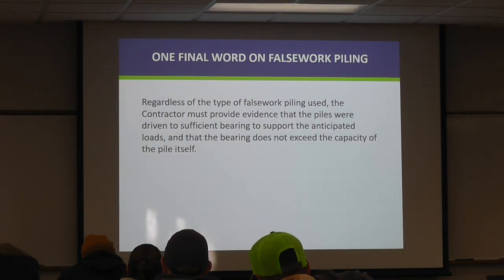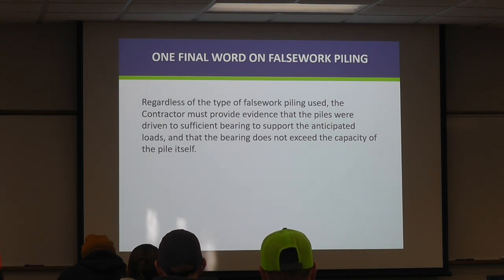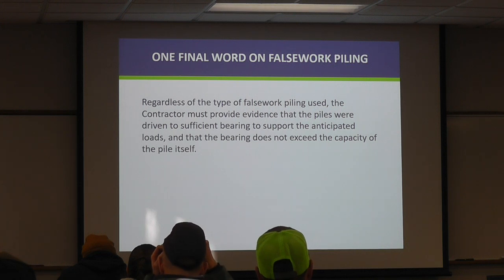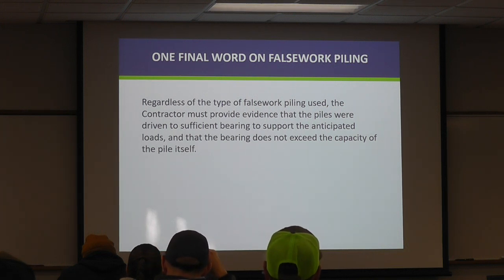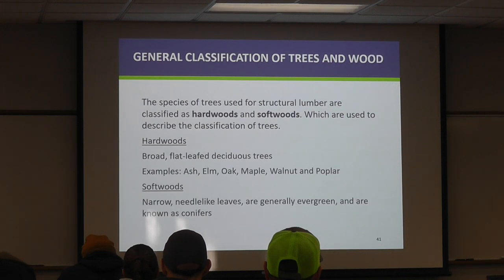So regardless of the type of falsework piling used, the contractor has to provide evidence that piles are sufficient. So they need to be running a PDA. They need to be running the MPF 12 formula for their piles. So make sure that those piles are sufficient and they don't settle under the load.